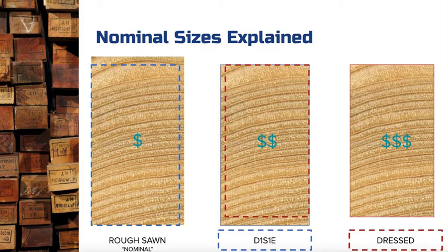And it's really important that you're aware of this language when you're buying your timber from the shop. Quite often you'll get a really good deal. You're like, wow, that was so cheap. But you'll get nominal sizing instead of dressed sizing, and then you have to machine it yourself. Now, without a jointer planer at the school, it's impossible for us to really accurately machine down your timber to a really high quality level. You're much better off spending the extra couple of dollars and buying dressed timber.